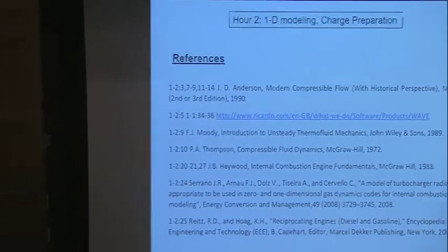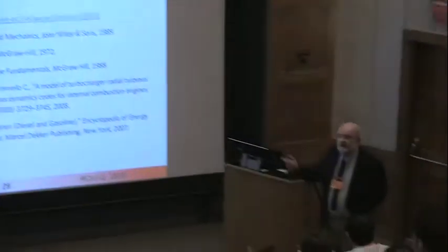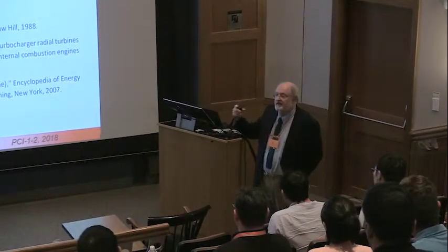Yeah, so it's very complicated, as you can see. I think I showed you one plot where we had a low pressure turbine and a high pressure turbine, each driving the corresponding compressors. You have to decide what the flow split is and optimize it for a given road load condition and engine speed. There's a team of 100 engineers, or maybe more than 100, working at BMW or VW or wherever, trying to design the flow system to maximize the amount of mass you can put into the combustion chamber. It's not a simple process.